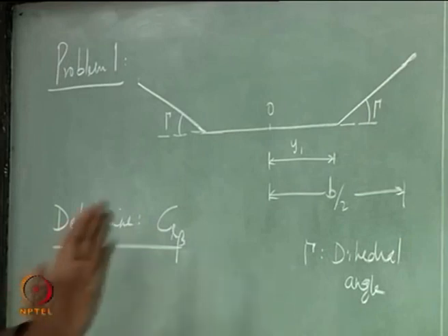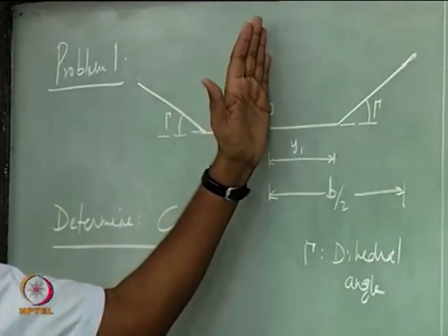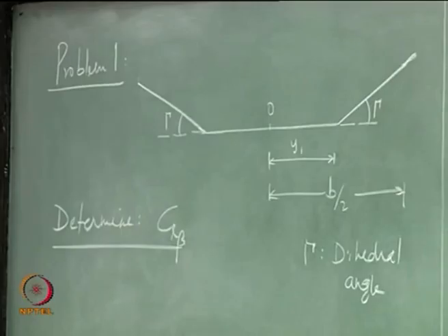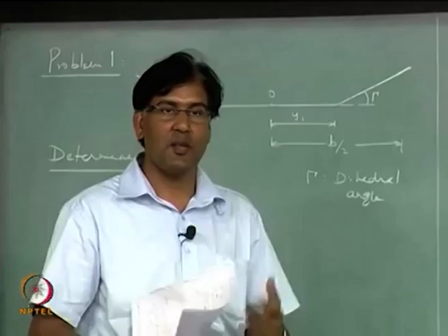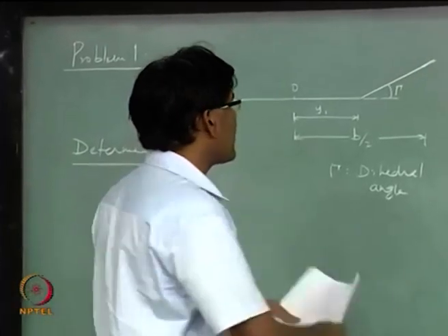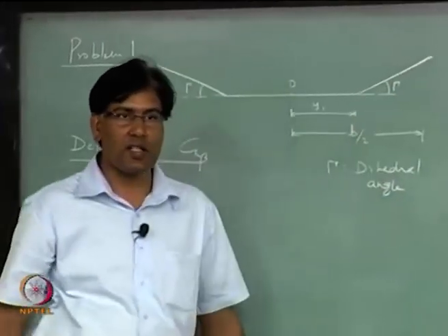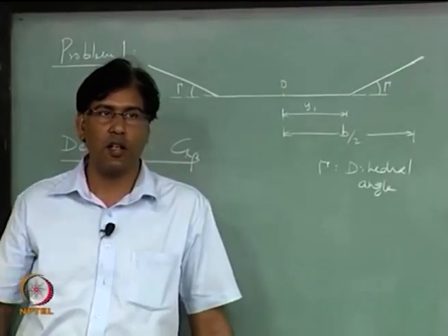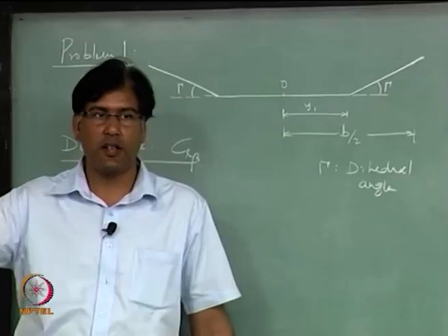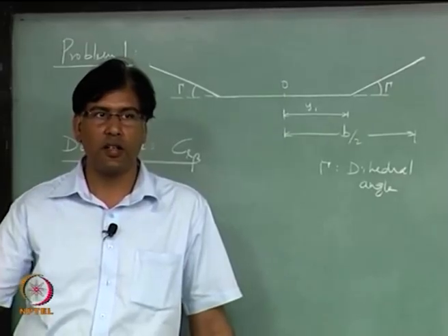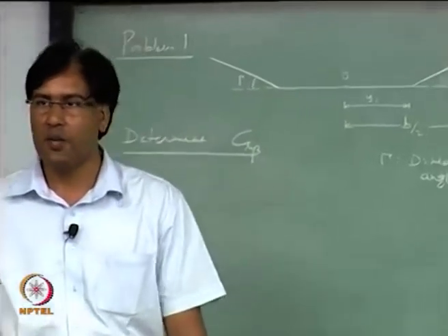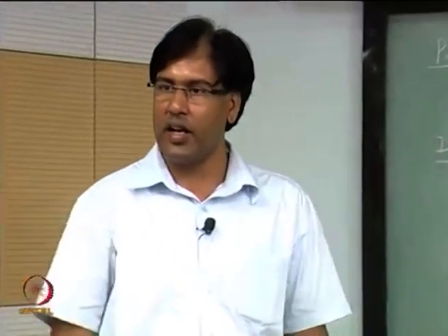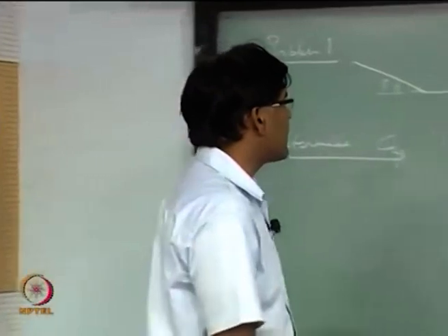Okay, about this. How do you go about solving this? I want to find out CL beta. So, I will assume that there is a beta, positive beta coming from this side, right. What is this side called? The right side of the wing? Starboard, right. The right wing into the wind is the starboard.